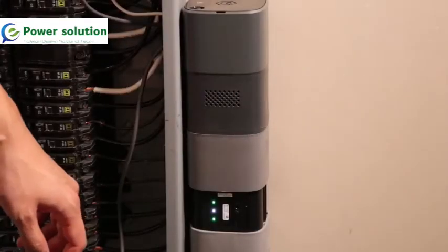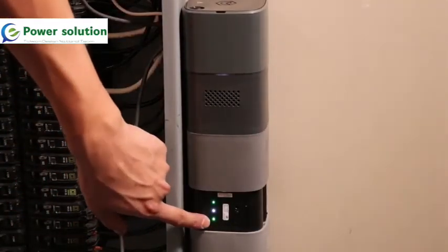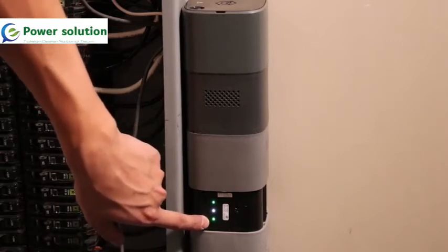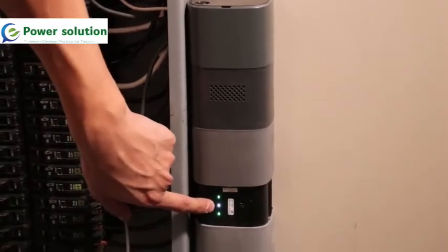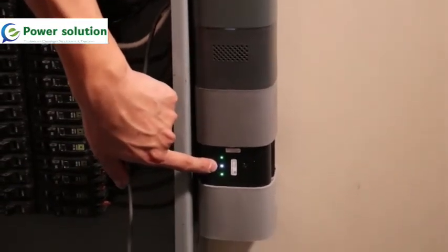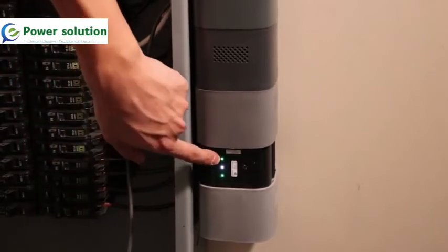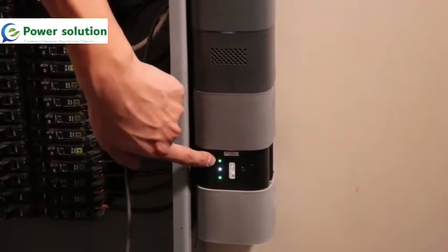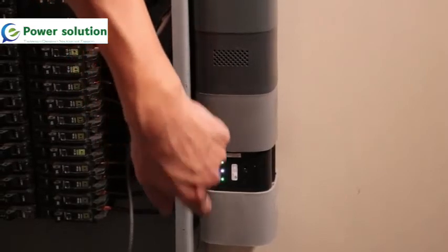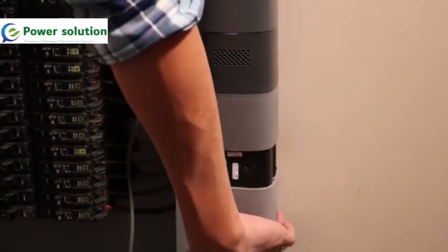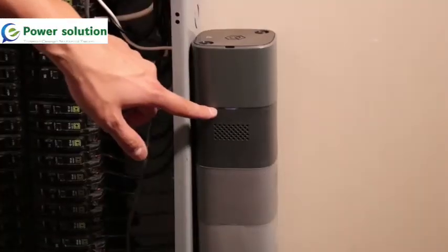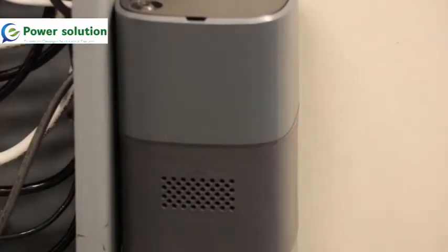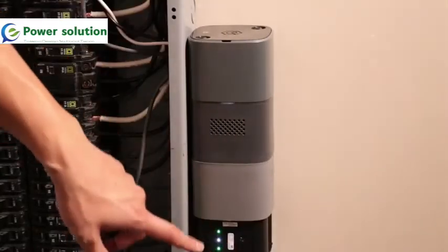Once your system is properly configured, you'll see a solid green light for the CT chain, a solid green or white light for the voltage connection. The color will be different depending on the type of voltage that it senses, and a solid green light for the Wi-Fi connection. If all three of these lights are solid green or white, this top indicator will show white and your system is transmitting. If this is ever red, that indicates that one of the subsystems is not properly configured, and you may open this to see what it is.